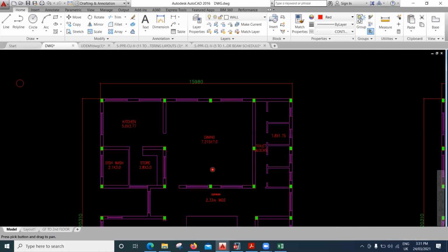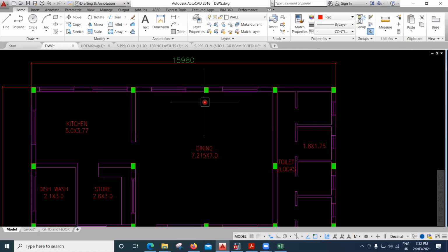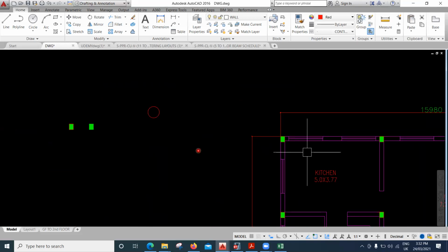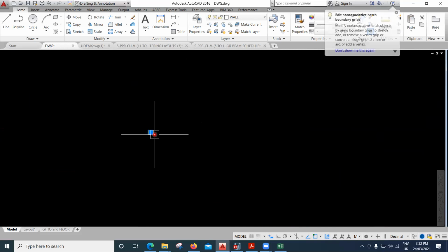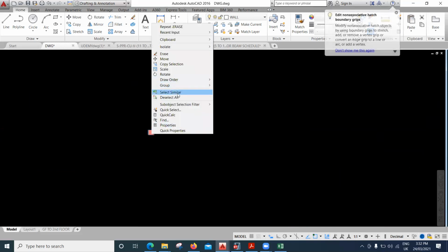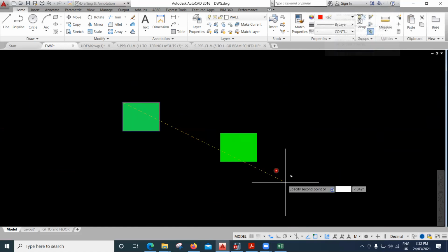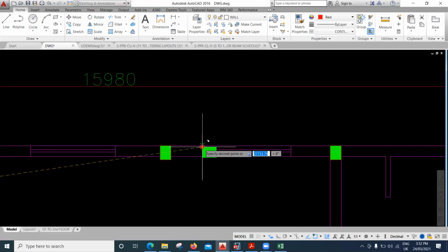So now the problem is that these two columns what we have here, it's creating an offset here. This is creating offset. The better option would have been we could have oriented this in a horizontal way, right? What I'm trying to tell is, let me orient that the other way around. What I could have done, I could have taken the orientation of this, and we'll say copy selection, and I'll click on this. I'll take the column from here, and we'll place the column in this way.